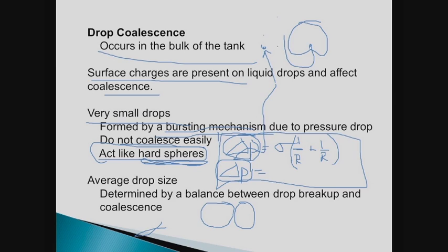If I have a tiny bubble, it might go into this from the backside, basically. There's a toroidal vortex sitting at the bottom down there as the bubble rises. Actually, it rises like this, and it goes this way. It spirals upward, and that's the effect of this toroidal vortex shedding itself on one side, then the other side, then the other side. So you have these very tiny bubbles, and then you have mushroom-shaped bubbles.